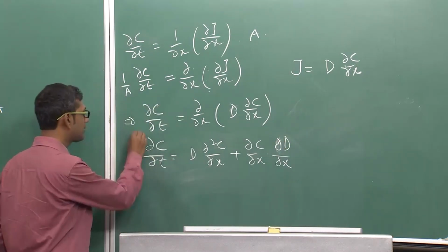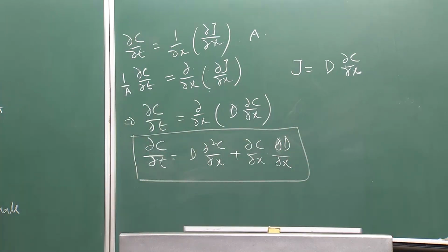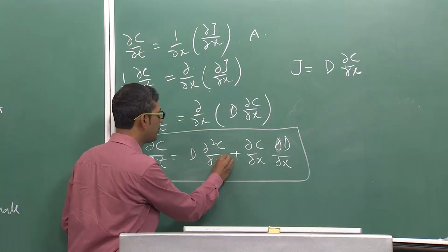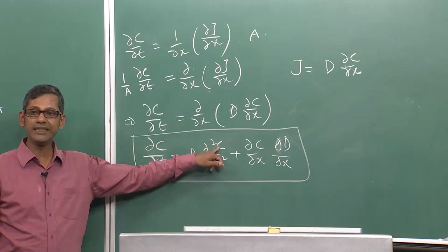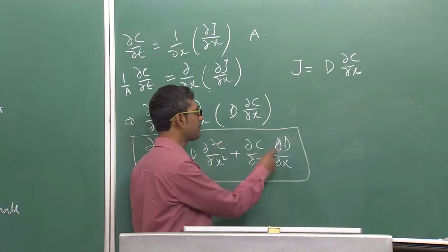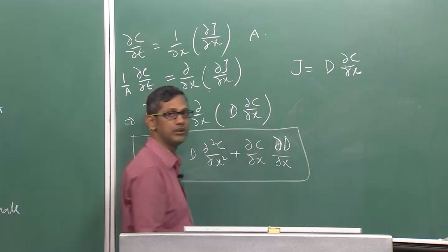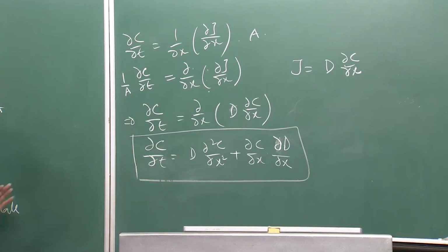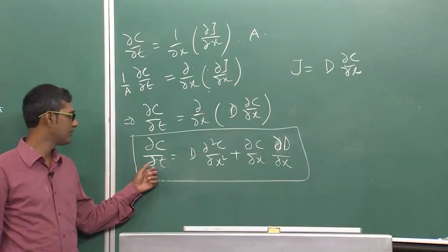Okay. So, that is actually a more logically correct expression of Fick's second law. In this case, you can clearly see we not only need to have the composition c as a function of x, we also need to have D as a function of x. The moment we have both these things clear from the experiments, we can solve this for c.